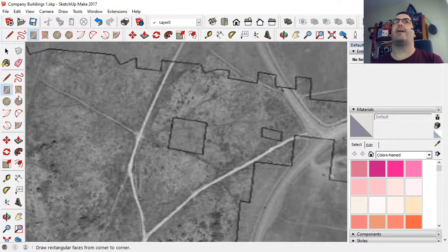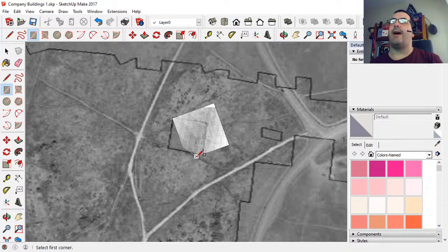So I'm just going to quickly put a pretend rectangle in there that represents our building. Now straight away you'll see that that disappears under there, and that's because I've got the terrain switched on as well. So when you're using this kind of methodology here in an application like this, it will respect the terrain also, just like it did before. So you can see if your building's sunk too far into the underlying land and things like that.